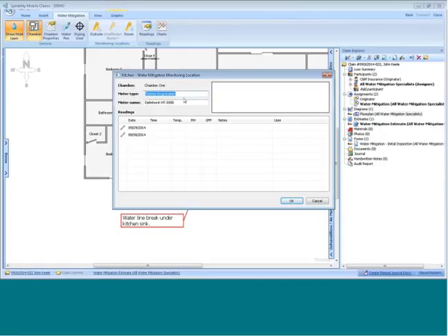The meter type, of course, is a thermohygrometer, and the meter name. This would default based upon your meter, so you enter it one time and you don't have to enter it again. And based upon when I set the job to start is how many of these dates I'm going to see. Obviously, I set the job to start yesterday, so that's what I would see, a blank. Most of the time when you start this, you're going to start the job on the day of, so you'll only have one date for a reading.